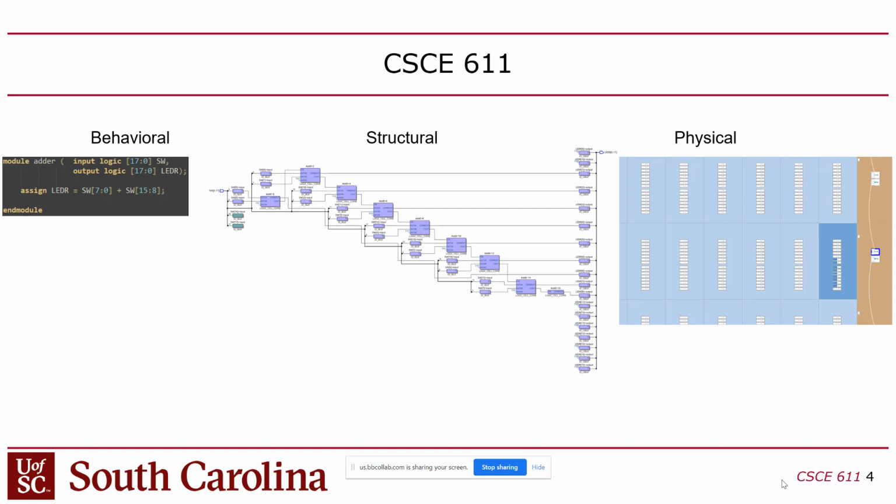Sometimes they're called EDA tools, electronic design automation. So in this class, we're going to use the same three styles: behavioral, structural, and physical. But the behavioral description is going to be specified in a high-level language called SystemVerilog. At least in the way that you actually enter your design, it'll be like writing any high-level code, like in Java or Python. And then we're going to use CAD tools to take that and compile it, or actually it's called synthesize, that description into a structural design.